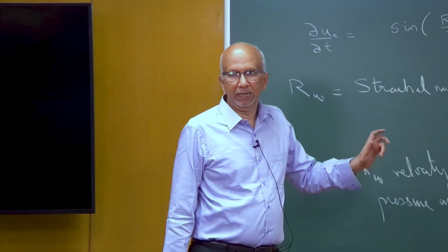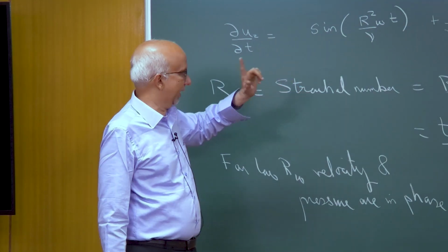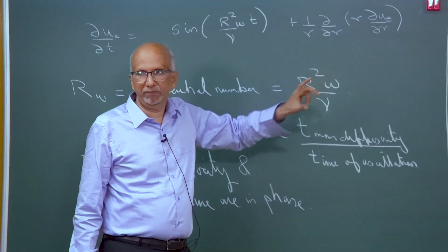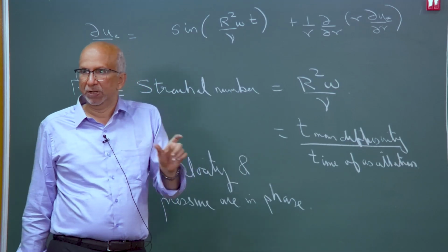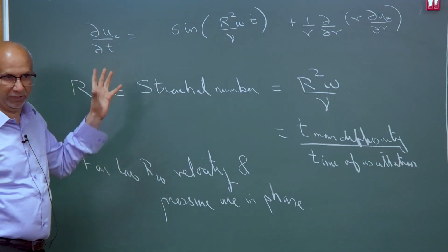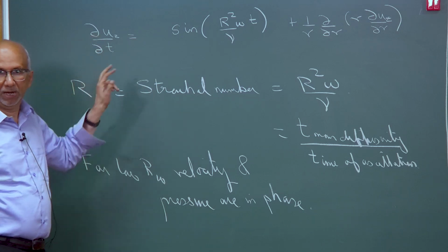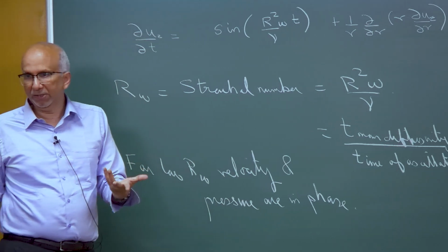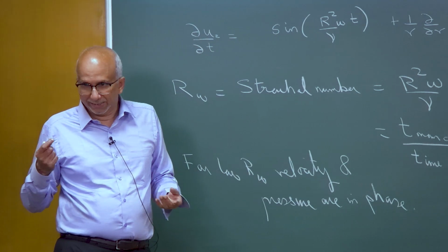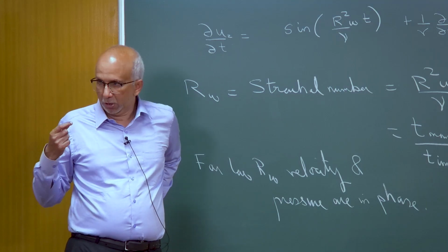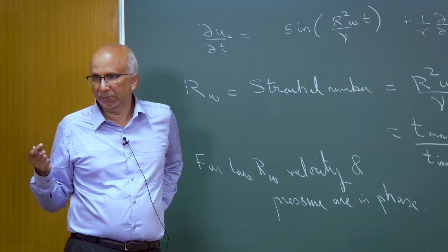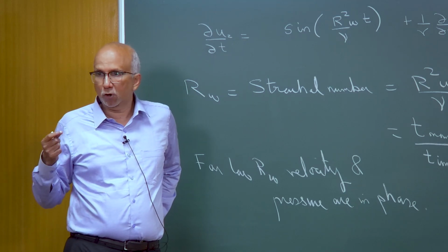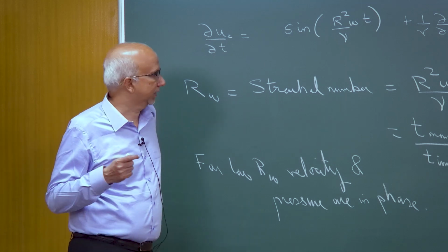So, when I neglected the time derivative term, the idea was the time derivative term in dimensionless form and this spatial derivative were of the same order of magnitude. So, because this was multiplied by Rw which was very small, I could neglect it, okay. Rw could be small, but if du by dt is large, I can't neglect it because that can be a significant contribution. So, there is an underlying assumption we make, the whole philosophy of making things dimensionless is this: all these variables, all these derivatives all have to have the same order of magnitude, okay. Just keep that in mind.